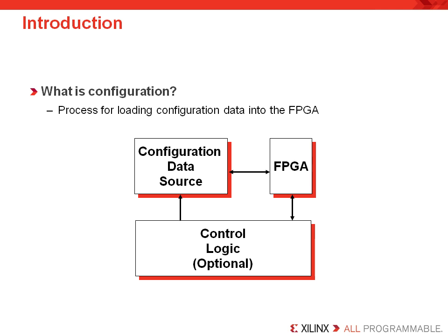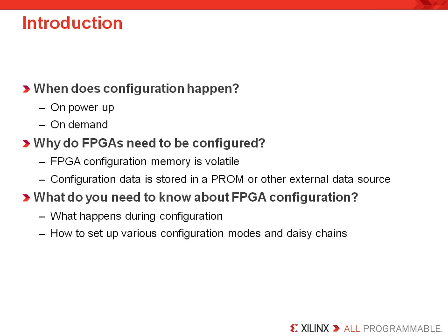So as I just described, configuration must occur on power up, but can also occur on demand by toggling the FPGA's program B pin. Additionally, configuration can be triggered with commands over the SelectMAP or JTAG ports without having to toggle the program pin.